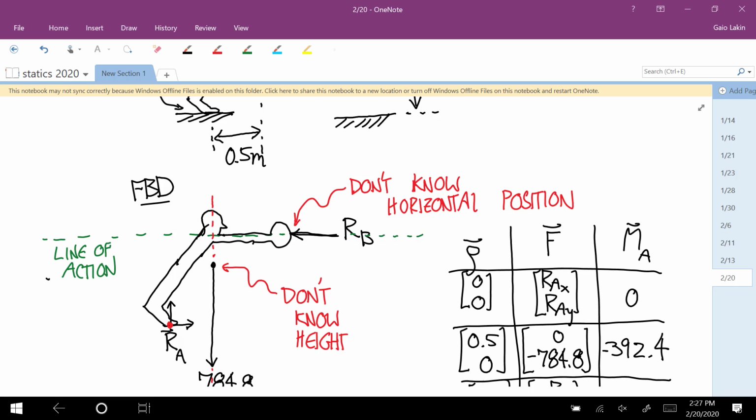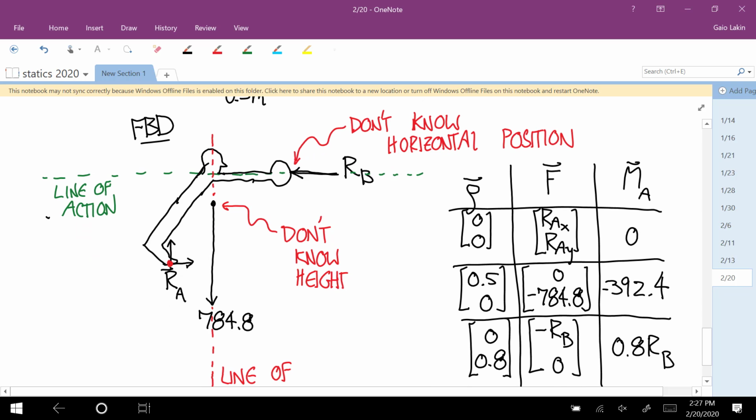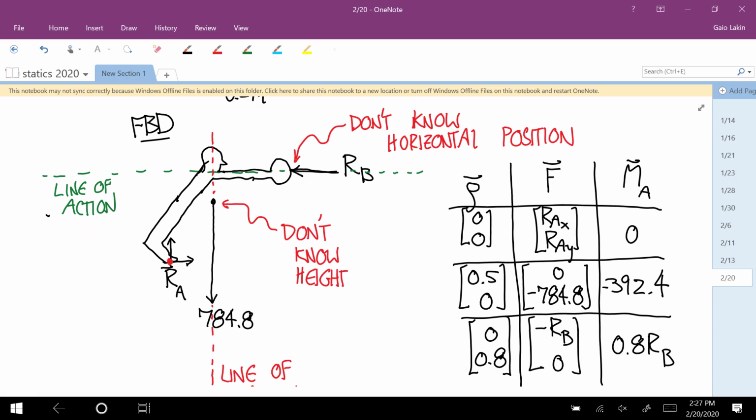We got to zero out components exactly because we had one vertical and one horizontal. If this was at an angle, we couldn't choose the component to be 0 because it's going to act along this diagonal line, and we'd have to deal with that diagonal line. This is a special piece that makes it simple, but you always can move it along the line of action. It's just not always convenient.